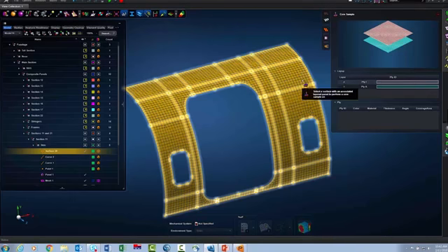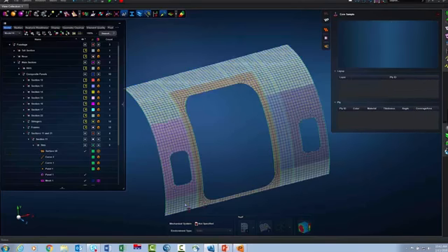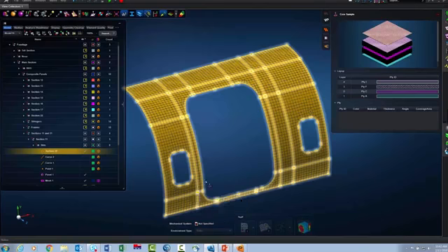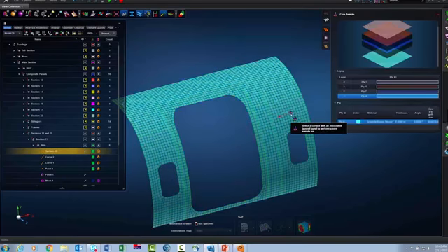The core sample tool lets us just mouse over regions of the model, and it quickly gives us feedback as to how many plies are there, what the plies are, what the orientation is, what the relative thickness is. In particular, I can plant at any particular location.